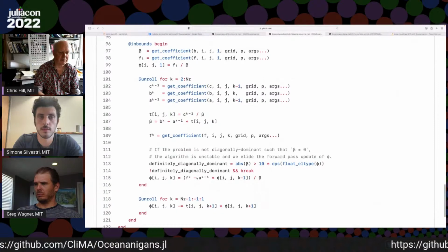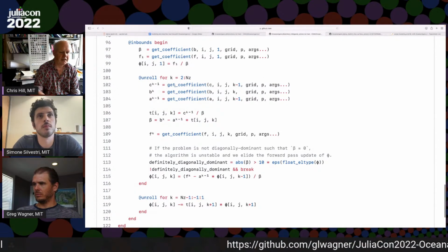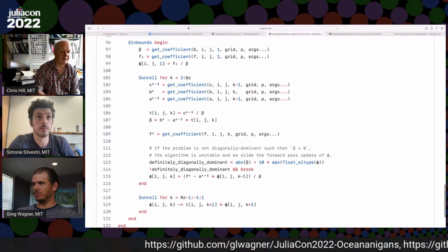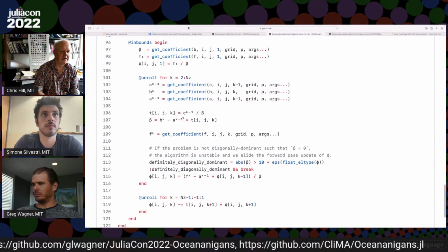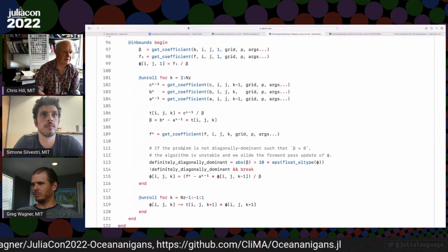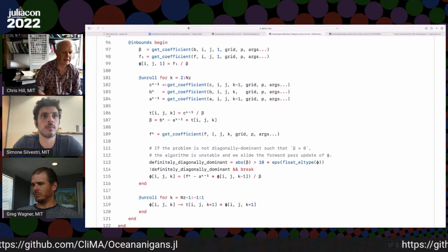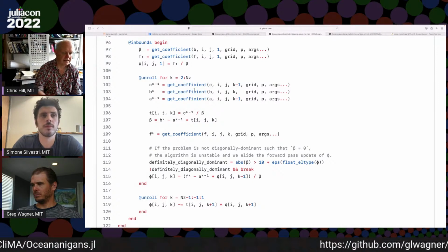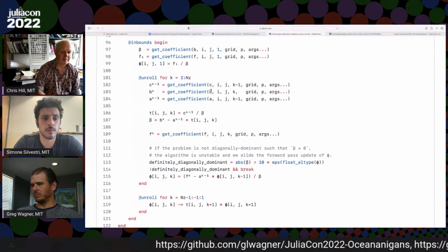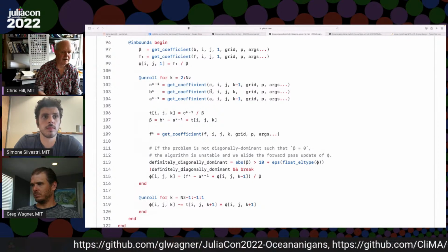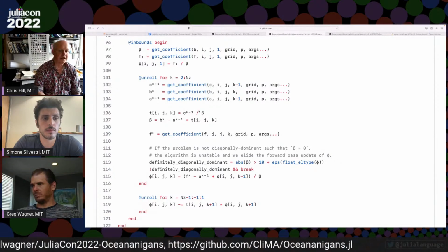Here we're explicitly looping in our own code in the solver, because the algorithm requires us to do that. That's part of the difference between these local operations and the global operations. And as we were saying, the coefficients can actually be functions. So there's some clever stuff that can go on depending on whether the grid is even or stretched, and that can all be embedded in these coefficients to try and optimize how this works.